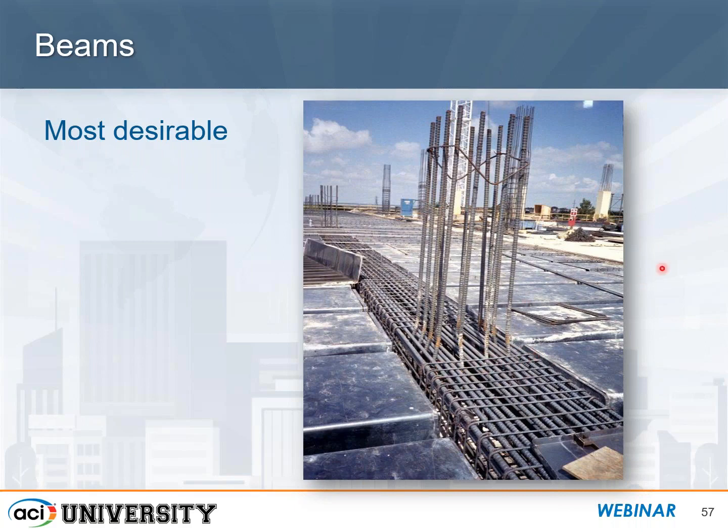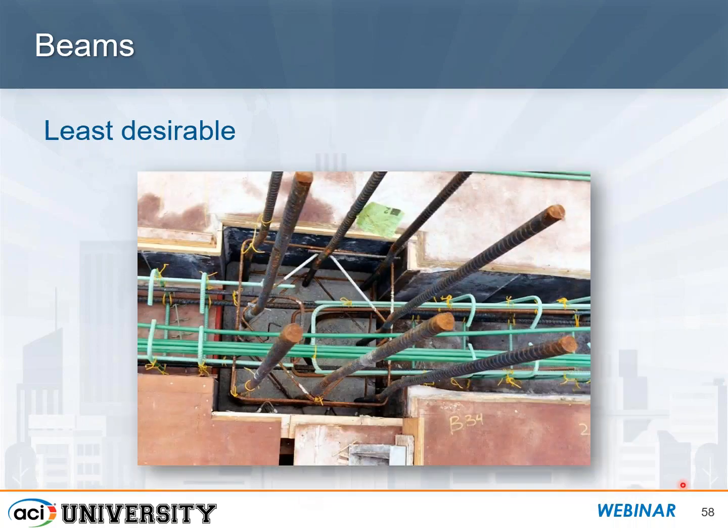These must be some fairly long spans, 40 to 45 feet. This girder's picking up a lot of load, and by having that girder wider than the column, that really alleviates any congestion or constructability issues at this joint. Whereas if you have this relatively narrow beam going into this column, you can see all of the issues that may occur at this location.